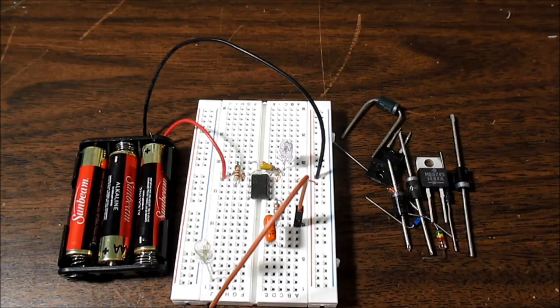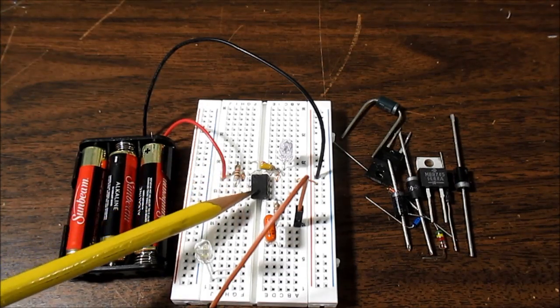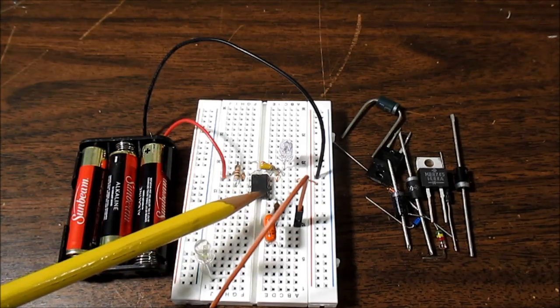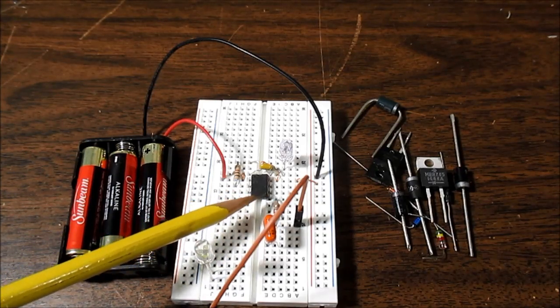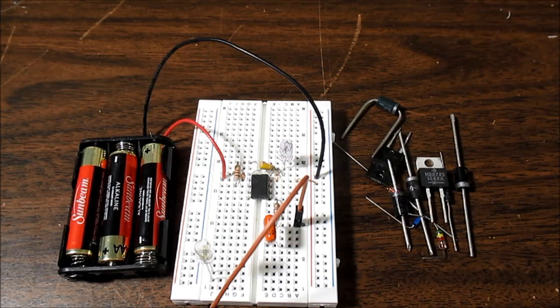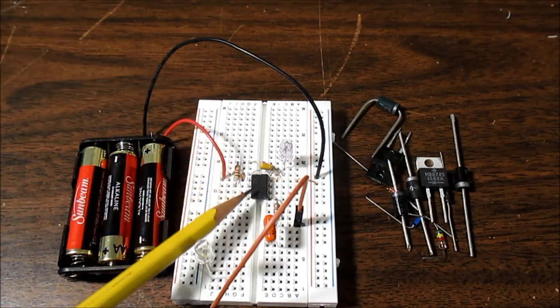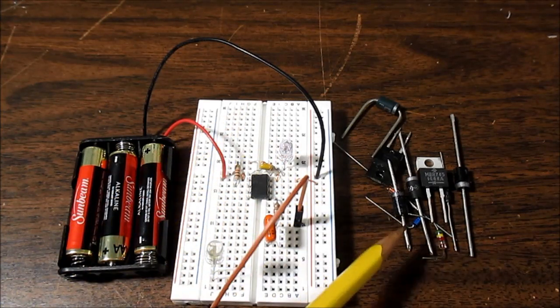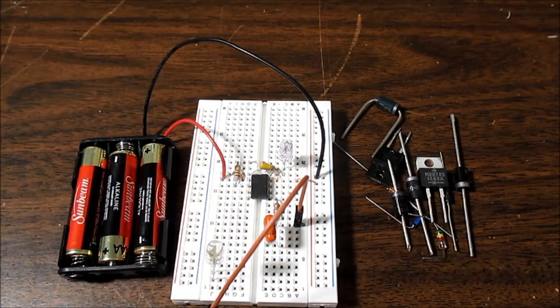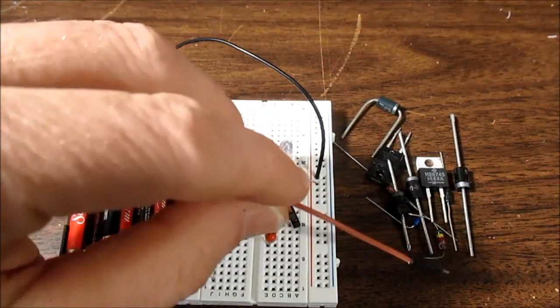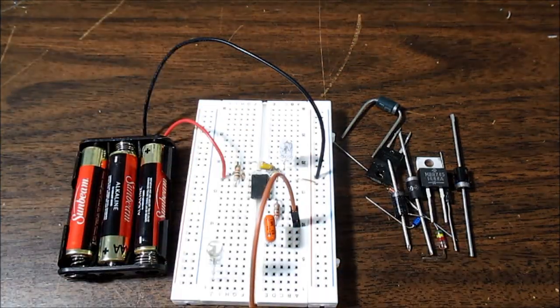Okay, I'm going to start with a switching speed test at 1 megahertz. What I have is a microcontroller, and I programmed its pulse width modulated output to give me a 1 megahertz signal or square wave on the output, and we'll use that to test the speed of these various diodes and see how they perform. One thing I found that's very important is to set up your scope properly.